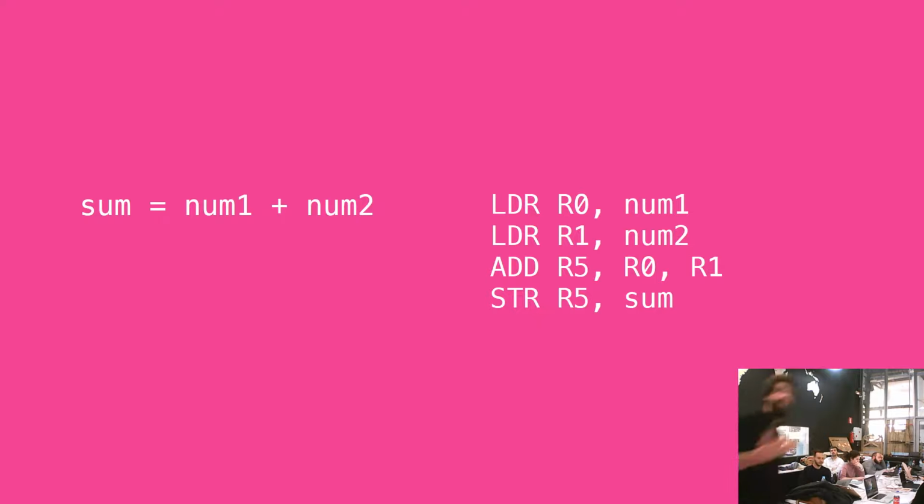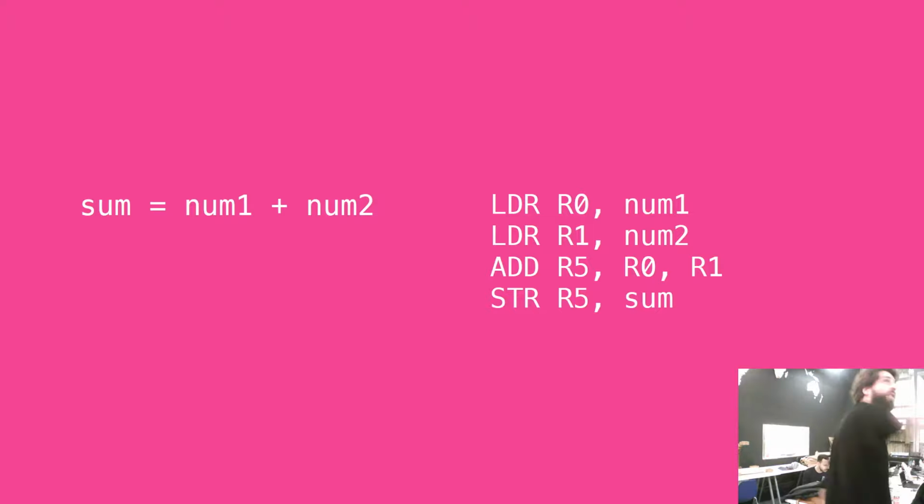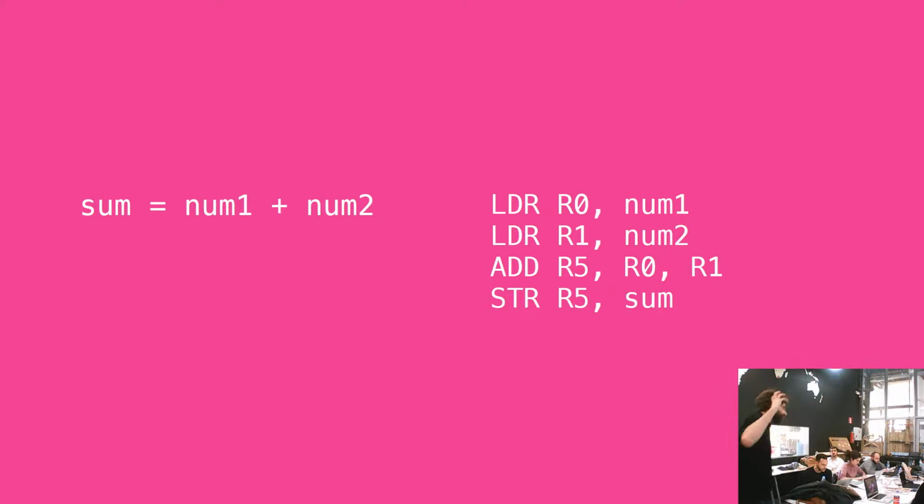So when we write code in C++, for example, for the Arduinos and for the microcontrollers, we'll be compiling code that looks like this into something that looks like this. And then from something that looks like this, we'll turn it into what's called machine code. That would be something like this, but represented in binary, so in zeros and ones. That would be what our memory would actually store. And when we put power into the microcontroller, it would start running one instruction after the other.